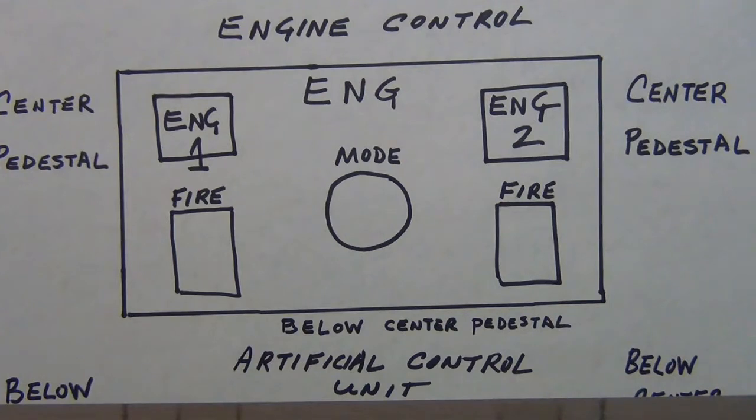Okay, and just a note, when you have the plane in a reverse position on landing, the ground spoilers are going to be deployed. That kind of makes sense, but I'm just verbalizing it so you have it in your head. And of course you have reverse full. So let's come in at the full aft reverse detent. And again, the FADEC is there to protect the engines. Therefore, when you're putting something in a full position, the FADEC gets involved to ensure the engine's not exceeding those RPM limits.